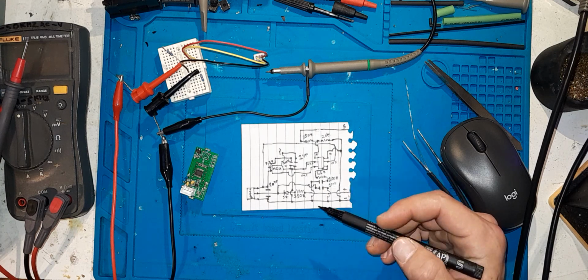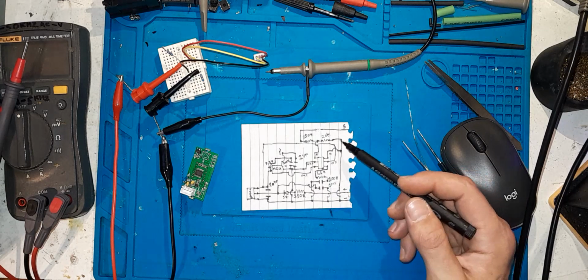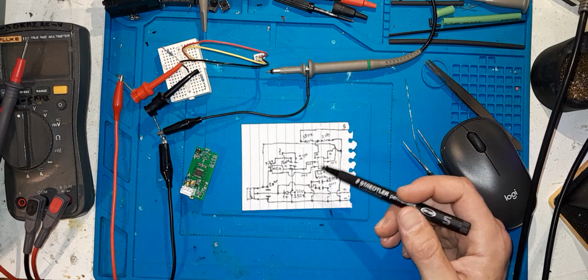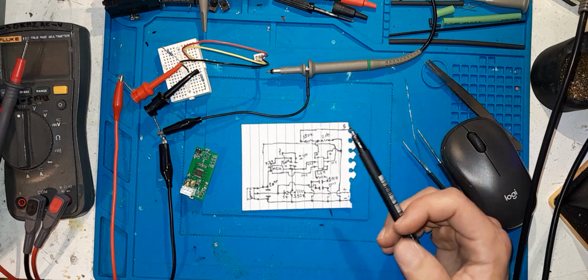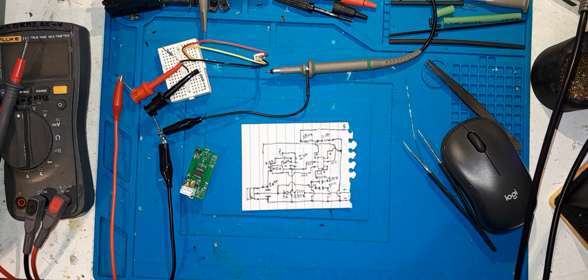I just can't see someone getting an op amp running off 3.3 volts, dividing a voltage down, and then just using the op amp as a comparing it against, I guess, the negative rail, and then spinning the value out into a DAC. It doesn't seem quite right, and this snubber doesn't seem right either. I think that is a specialized part.